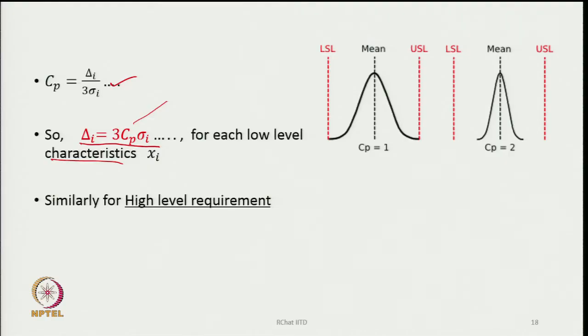So, we know that whatever we do, this particular non-woven machine always gives me a Cv of 10%. If I know the Cv of 10%, we can find out the standard deviation also. That means the process is capable of producing that much only. If I demand a value of 5%, then the process will not be able to give me that.